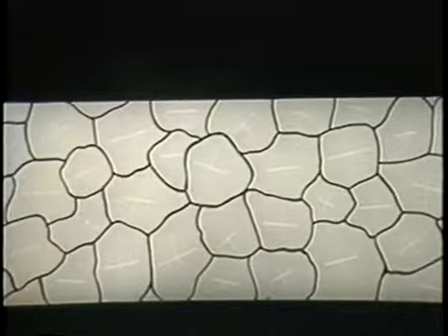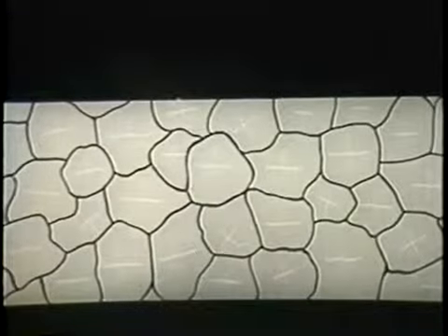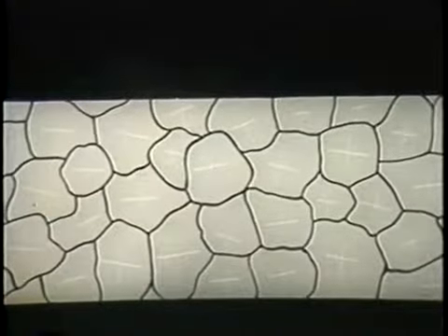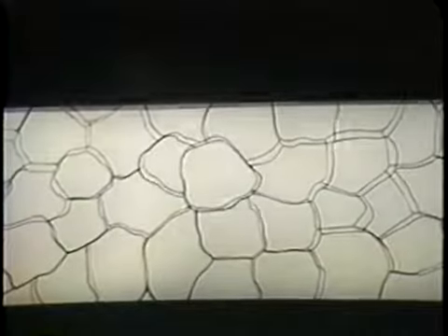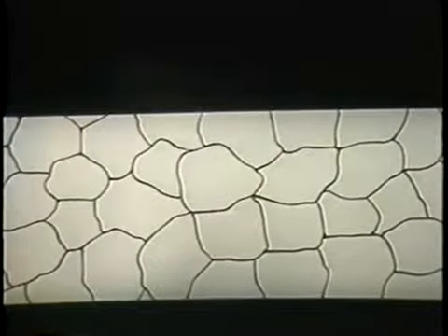Under the type of load applied in the bending and stretch forming processes, the grain structure of the aluminum alloy changes in a manner similar to that shown for the cold rolling and stretching processes. The grains rotate along the active slip planes and become elongated, and the metal is strain hardened.